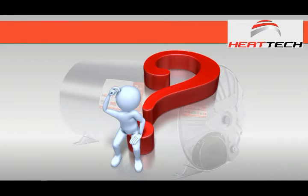Yes, he can do that, because the standard says they must be equal, provided the valves are less than the pressure rating of the geyser. All the valves in the system. So yes, the geyser must always have the highest pressure rating of all the components, the same as the rest or higher.